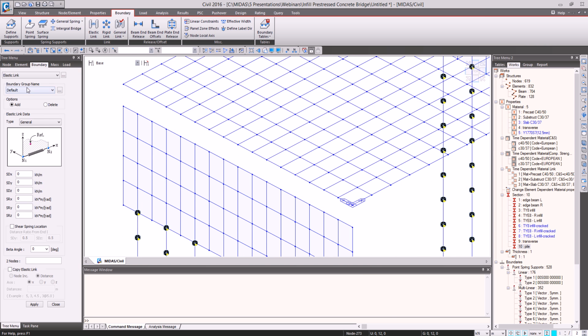We'll use elastic links for this. Firstly, the simply supported condition. I'm restricting all translational degrees of freedom and torsion. Elastic links have their own internal coordinate system. So restricting SRZ for these links actually will restrict the torsion for these beams. We want to make sure that this won't give any instability when we activate the elements.